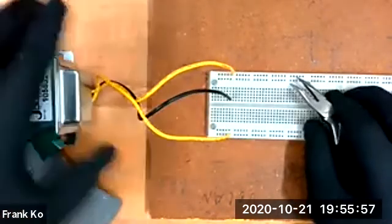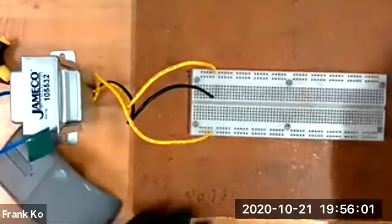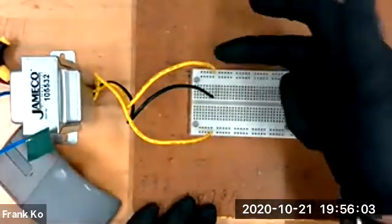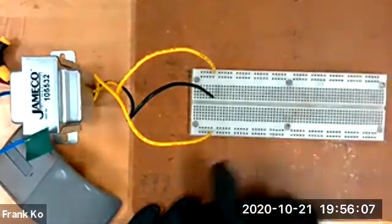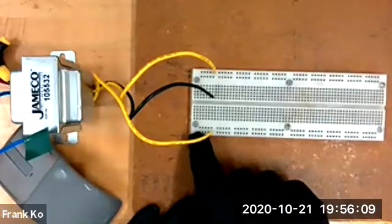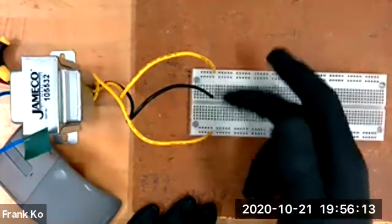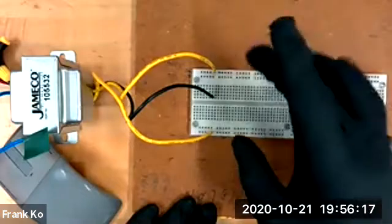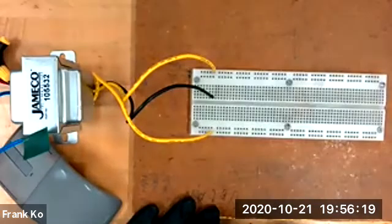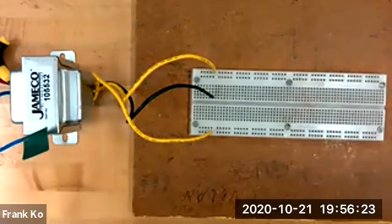Okay. Are those now secured onto your board? And they are, so we have one secondary on a power rail strip. We have another secondary on the opposite power rail strip, and the center tap is on any tie point in between. Do not have the secondaries connected together, right? If the secondaries are connected together, we will have havoc.